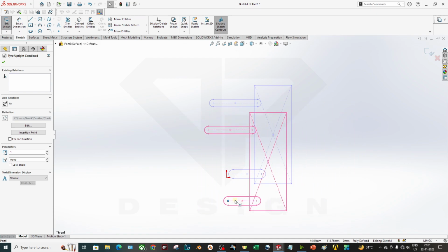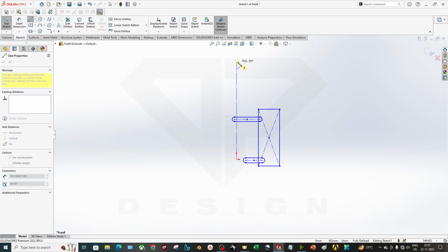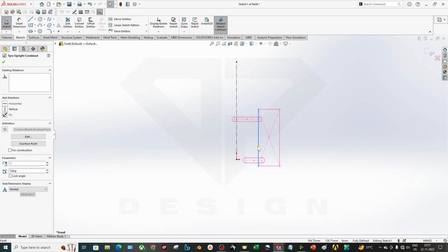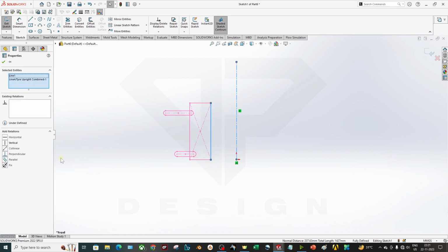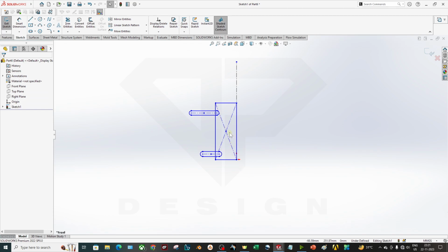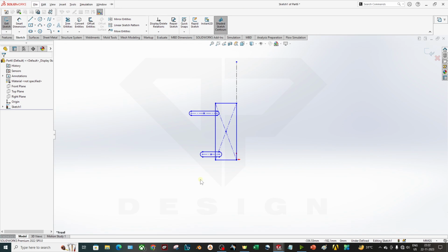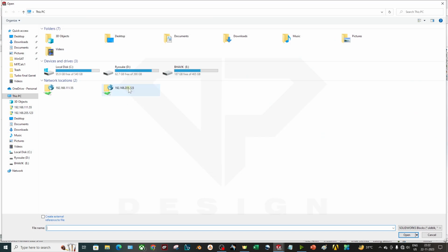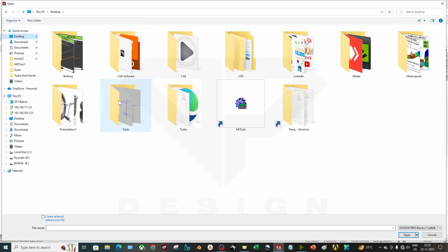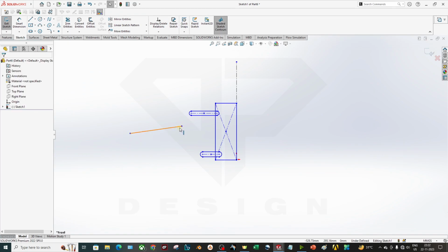Now you can place it anywhere right now, and you can do a sketch also for constraining this. What I will do, I will just make this one, and I'll make this line collinear. So what it will do, it will move like this. Okay, good. Now I will insert my wishbones, right? So I will insert my wishbone over here.